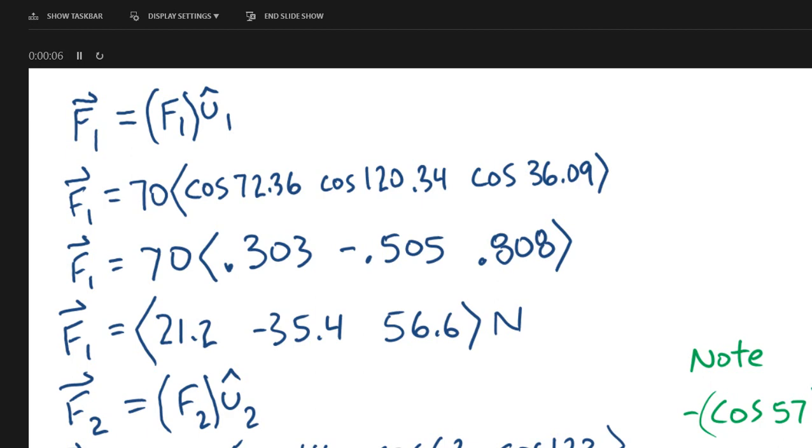The one thing that might be a little bit confusing there is this one dimension, the 57 degrees is with the negative y-axis, excuse me, negative z-axis. Like so. To get the true gamma angle, which is the angle that the vector makes with the positive z-axis, you'd have to take 180 minus 57 and get 123. Okay.